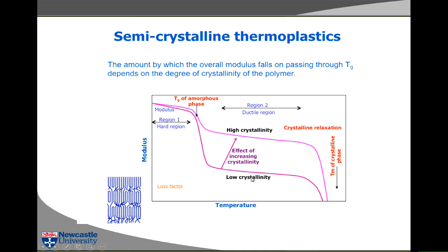If there are not many crystals there, you have a low Young's modulus. And again, the best example of that is polythene, because there are different types of polythene. The polythene that we deal with in pipes is what we call high density polythene. It's a density of about 0.96 or something like that. Specific gravity rather, 0.96. There's another polythene called low density polythene, which has a lower density of about 0.92. So it's only the difference between 0.92 and 0.96.